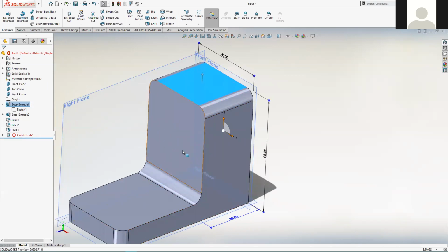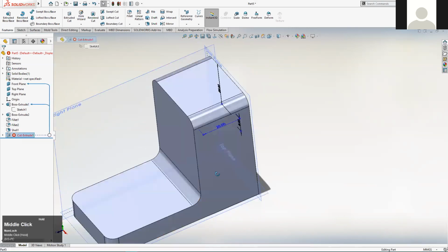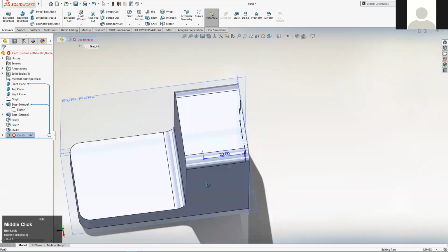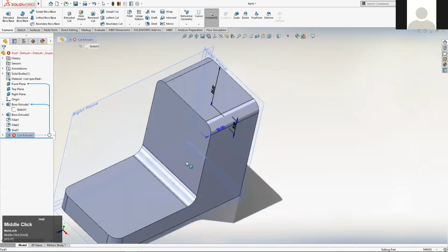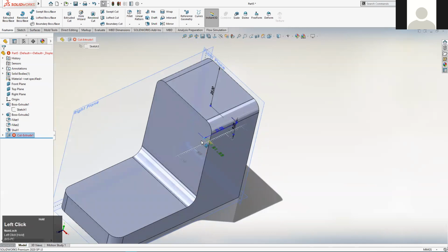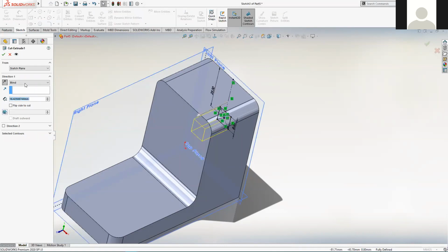If you set these extrude cuts, which you intend to always pass through the part, to a set depth, it's not very adaptable to change in the future. So other bits of the part may get changed, and your extrude cut that you intend to pass all the way through the part doesn't go deep enough anymore. So at that point, you could go back in and change the depth of the extruded cut. But that's a lot of unnecessary work when you could have just set the extruded cut to one of the sort of logic-based options. So that would be all these ones.